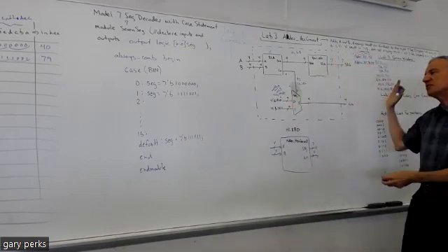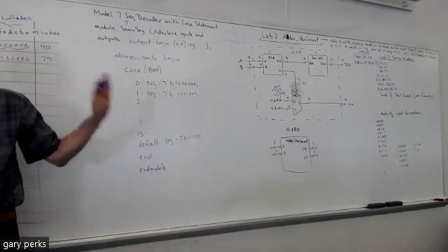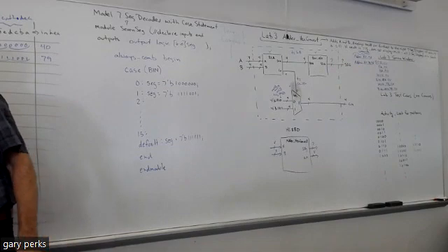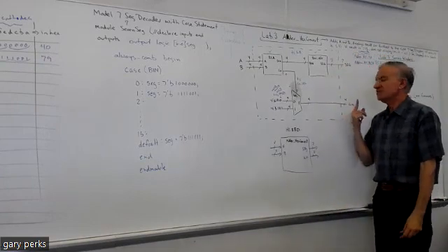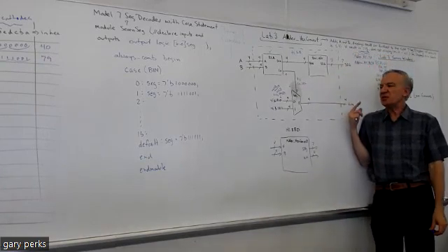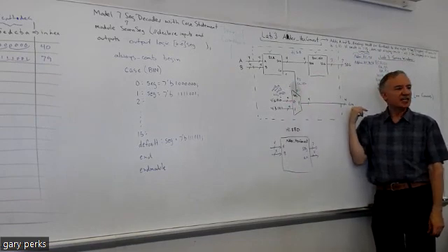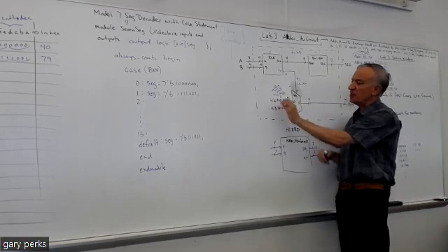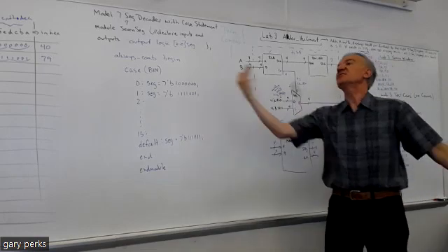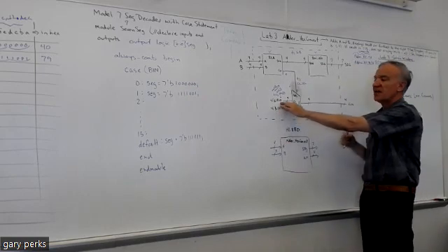So that means my furthest to the right display is going to get a 0, which is going to make the other side a 1. The other 3 displays, they're going to get 1s, which is going to make the common anode part a 0. So what does that mean? What am I going to see on my Basys board when we have 1, 1, 1, 0 going to the anode of the 7-segment display? From the power. Yeah, the furthest to the right. See, if I had 0, 1, 1, 1, like if I had reversed this, then the 7-segment furthest to the left would light. But we want the one furthest to the right. So that's why this is a 0.